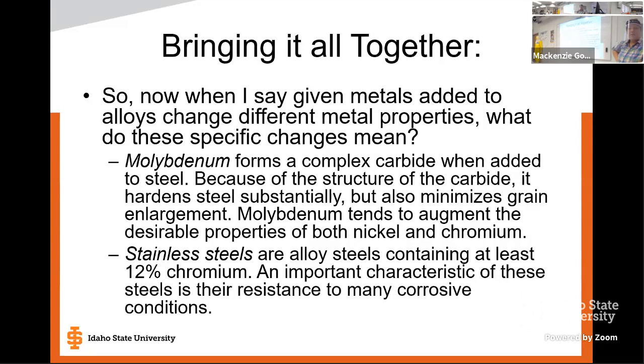Something that needs to resist scratching because it's visible and part of a look, but is also under stresses. Will you say again why large grains are bad for cracking resistance? The larger the grain, large grains are more prone to corrosion and stress corrosion cracking.